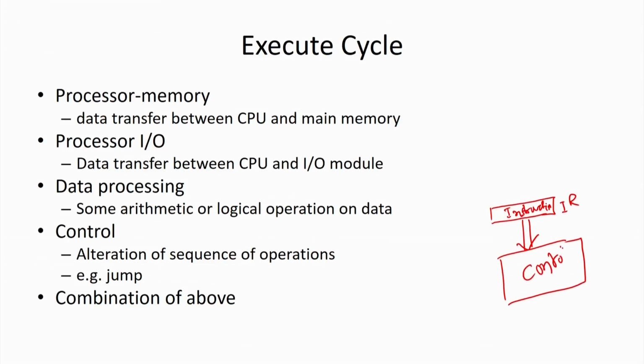So, we have a control unit inside the processor. Now, this control unit is going to generate different control signals, and those control signals are going to control different components, or perform different tasks. Like in the fetch cycle itself, say PC is transferred to MAR.